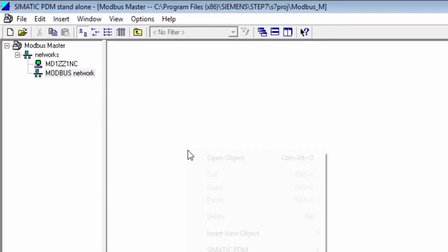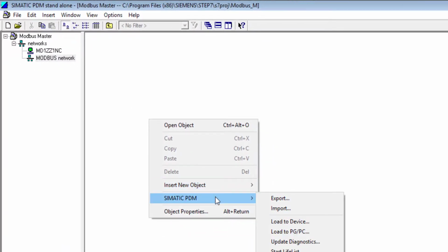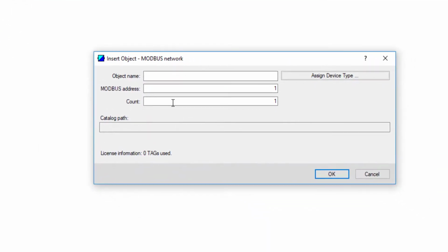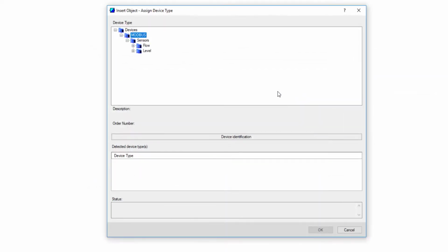So we've got that. The next stage is to insert the instrument. And for Modbus, the default address is 1. So that's HART, your default address is 0. For Modbus, default address 1. So as long as nobody's reprogrammed that, this should work. Again, you're going to have to check on the instrument.